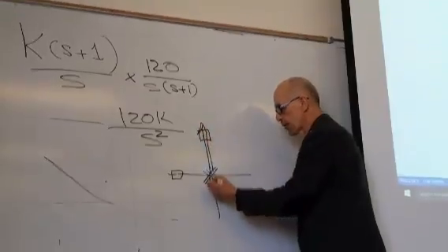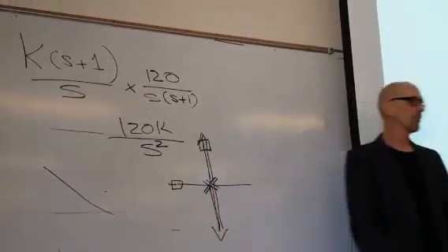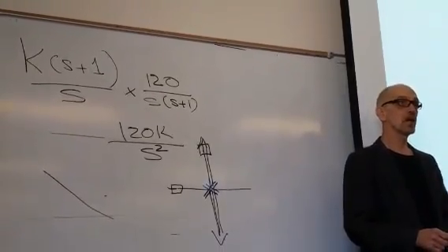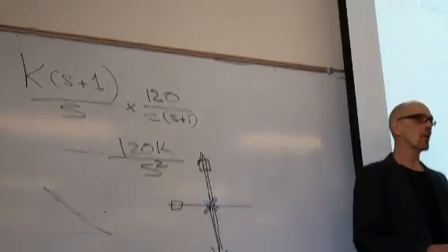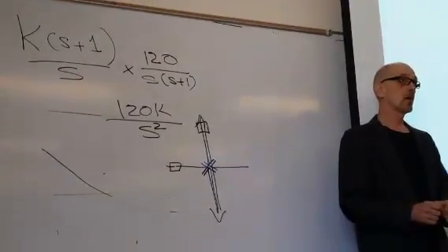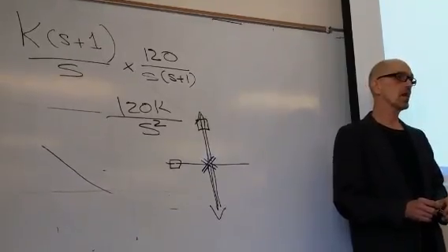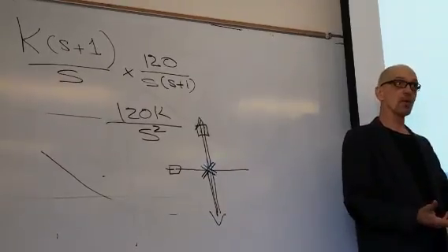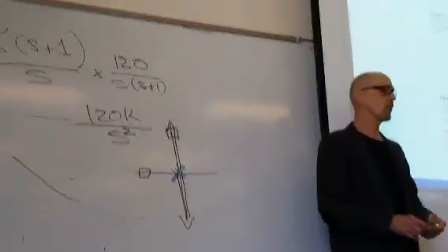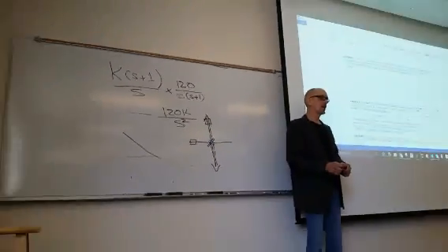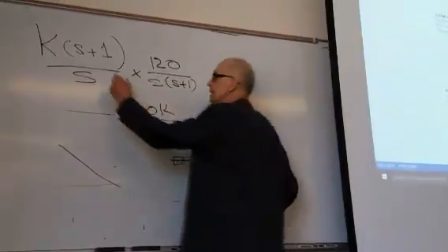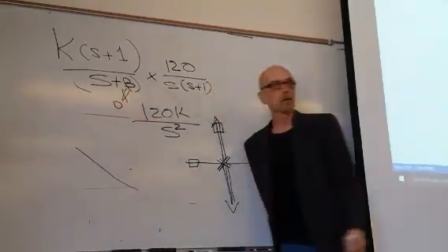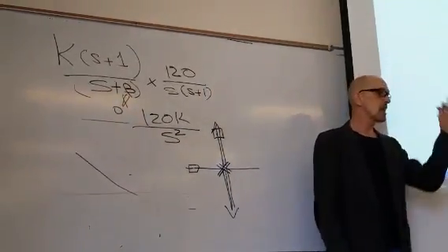Now tell me about the closed loop steady state error. Tell me. There is none. Remember, to compute steady state error, you actually have to have a stable system. Just because you get a finite number for a steady state error does not mean you will have a steady state error if the system is unstable. You'll still get a number, but the number is irrelevant. So be careful with it. You have to have something that looks like this, where this is non-zero, or everything beyond that point won't work.